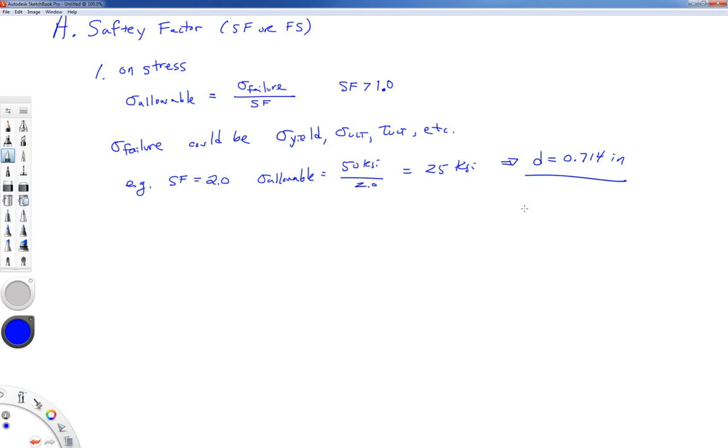If you know more information or have more stress analysis available, you can reduce that safety factor. So a component on a car might have a safety factor of 1.5 to 2 maybe, depending on what component it is. Vehicles are very sensitive to fuel economy standards, so you don't want any extra material, but you may want to have some safety built in.